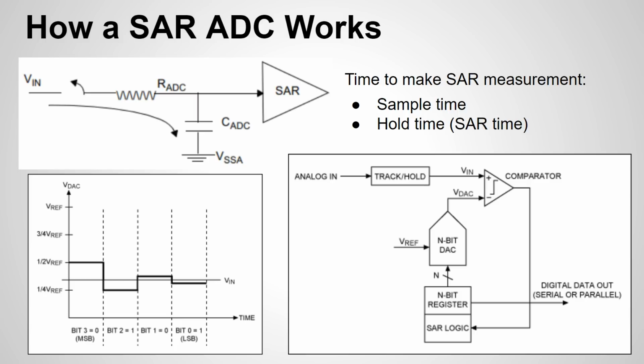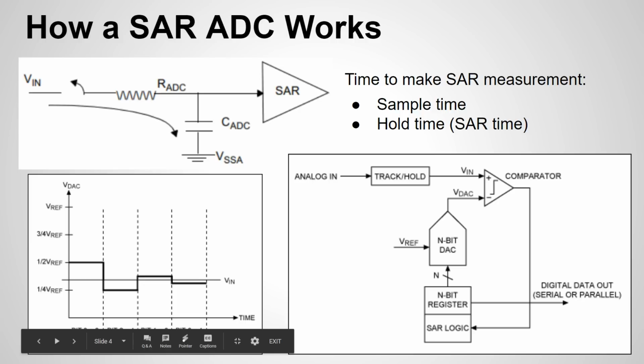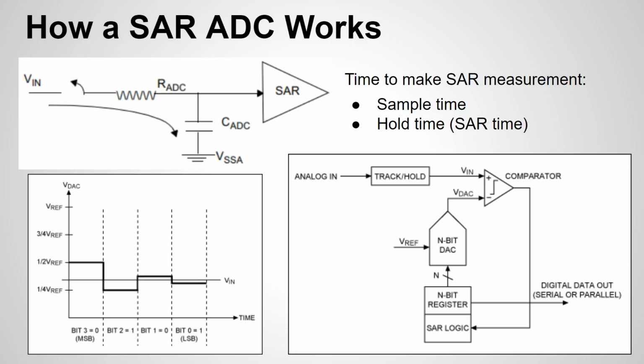by the output of the comparator. The other thing that's used and that's important is a DAC, a digital to analog converter, that's built into the ADC. So it's based off of the reference voltage. Remember, we talked about that in part 1, how important it is to have an accurate reference voltage. And then the DAC, using this reference voltage, divides it down to smaller values to slowly close in. You can almost think of it as divide and conquer to find what this Vin value is that we're getting from our charged capacitor. And you could imagine, since we have to do this comparison multiple times, this has a very high input impedance because we don't want to drain the signal from our capacitor that's charged up. And remember, when this is happening, the analog signal is isolated.